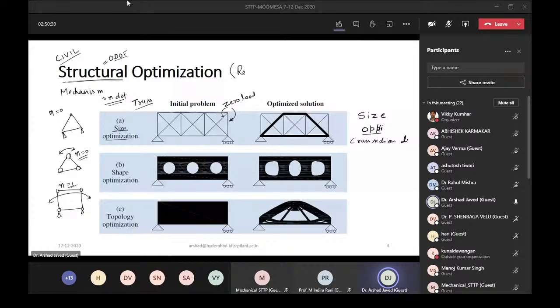design. It means, suppose we have taken a circular member, okay, circular bars which are used, or you can take L shape, which has been considered here. So you can take L shape or whatever shape is there, and you can decide what should be the cross section area, diameter, length, amount of material which can be deposited. So the member which is taking the highest load should be more thick compared to the members which are taking 0 load or no load. Okay, 0 load or less load.